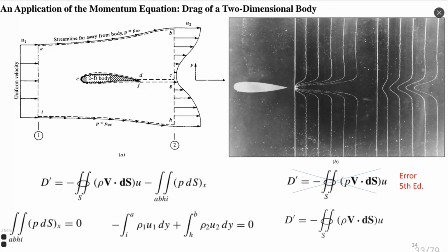So instead of reaction force, we have drag force, and we have a balance between this drag force and the momentum on entrance and exit from this control volume. This balance of forces we might find in this equation here. It's also shown that the pressure forces at a far distance from the airfoil are equal to 0. So we are not considering this pressure balance far from the airfoil, and we consider just flow inside this equation of drag. We consider just the flow of momentum through inlet and outlet.